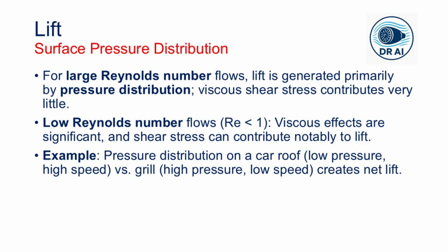at high Reynolds number. At very low Reynolds number, think microscopic organisms swimming or tiny insects flying, viscous effects dominate everywhere, and shear stress can be as important as pressure in generating lift. But for our purposes, we will focus on the high Reynolds number regime where most practical lift generating devices operate.